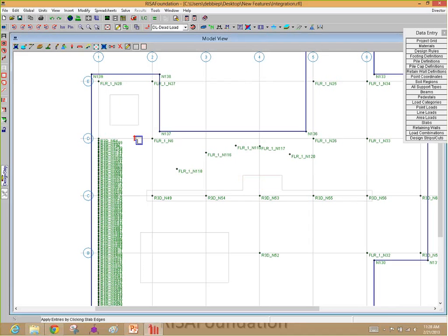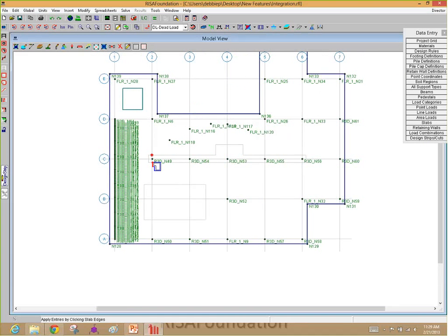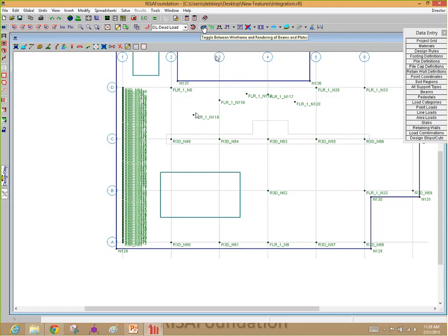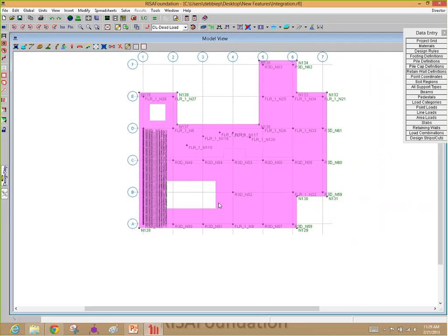I'm just going to say apply, and I can just click on that background DXF to create this different area here. Click on it, last click closes it, and it turns this blue, this aqua color for me to show you it's an opening. I'm also going to drop an opening over here. Just going to put a couple openings in my structure, so in my slab there. When I have those openings in place, I'm going to double check and show you where it's rendered a little bit more. You can see that that is an actual opening in the slab.